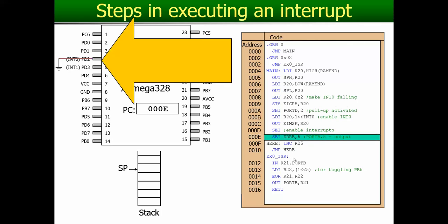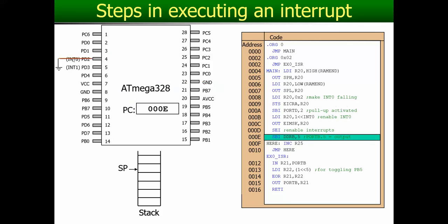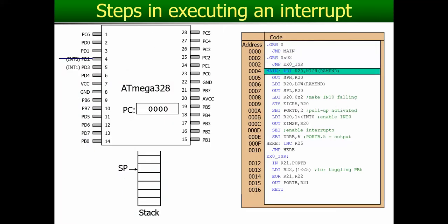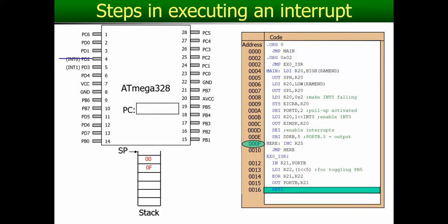And let's say we're in the program, and that pin goes low. Oh yeah, wait a second, why are we interrupted on 0? Yeah, falling edge. So we were high, and now it's connected to ground. When it's connected to ground, the transition from high to low occurs. The falling edge arrived, and now we have to leave where we are.